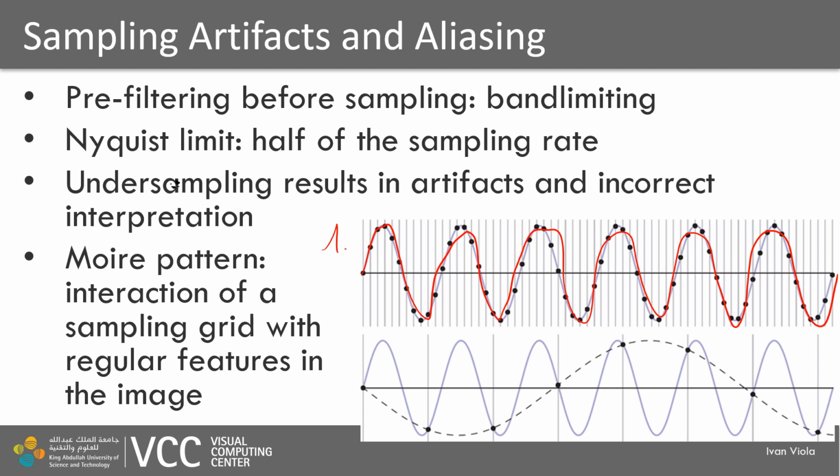So the samples are representing this function sufficiently. The situation is quite different at the bottom, in the second case, where our number of samples is much more limited. While we have here 1, 2, 3, 4, 5, 6, 7, 8, 9, 10 samples, we have only one sample per such an interval of 10 samples. So this is heavy undersampling of this function.